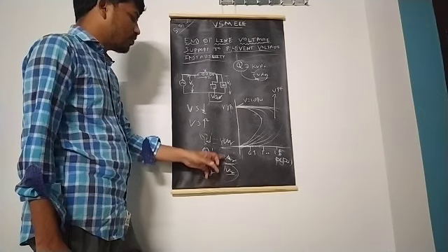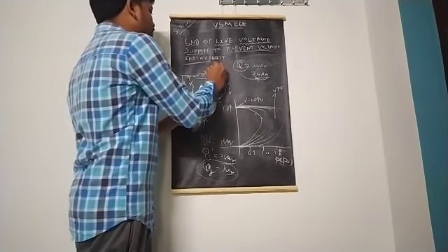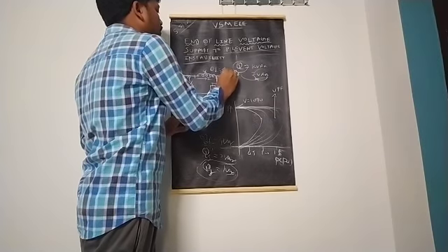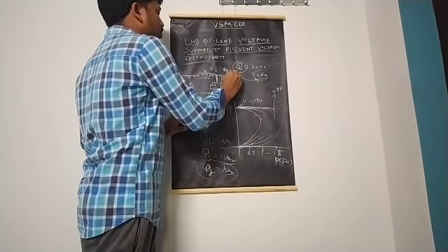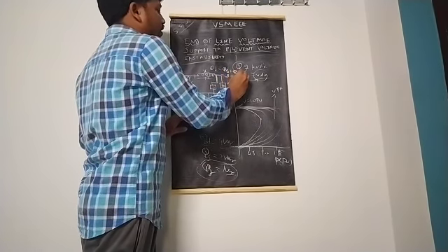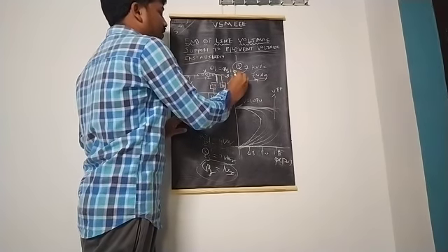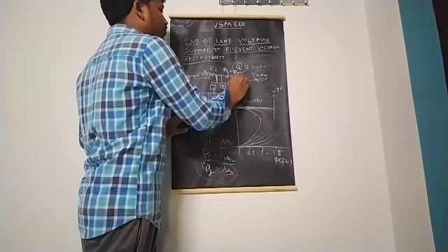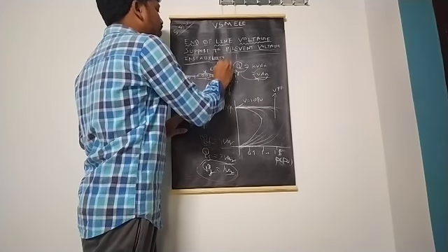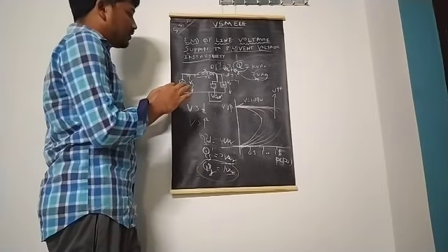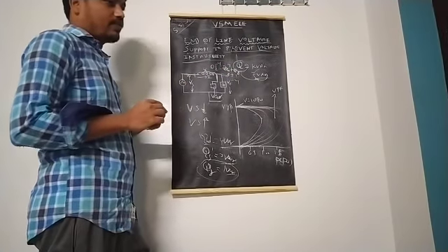Therefore 3 plus 1 is equal to 4. That means Q demand is equal to QC plus QR, that is QS plus QR. QS is the 3, and the Q required or Q supplied by the reactive power component is 3 plus 1, which is equal to 4. Therefore Q demand is already 4, so 4 is equal to 4. That is the importance of this reactive power compensation.